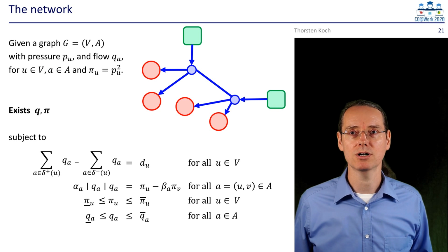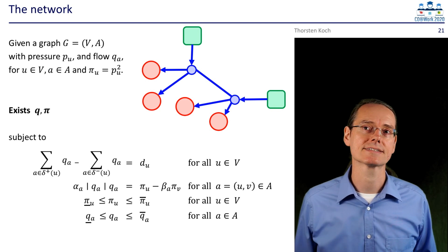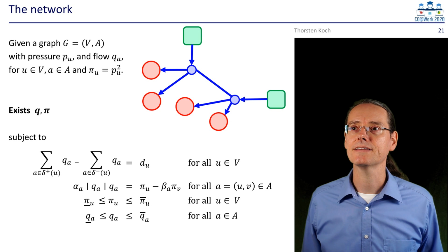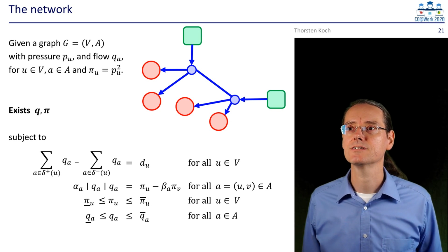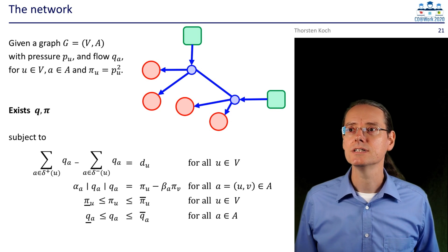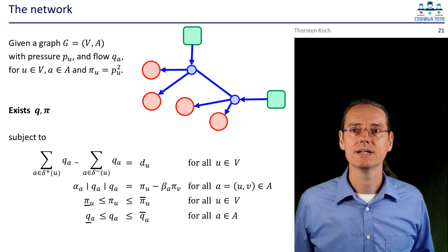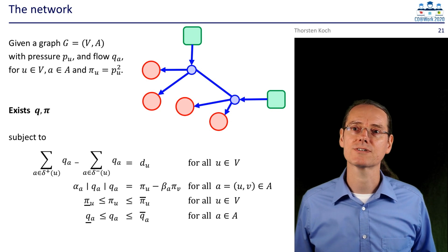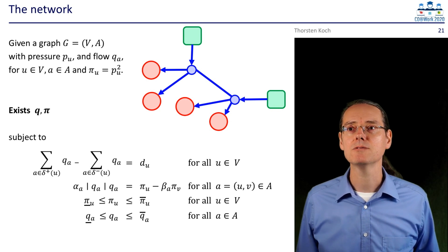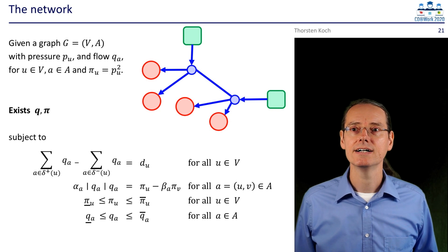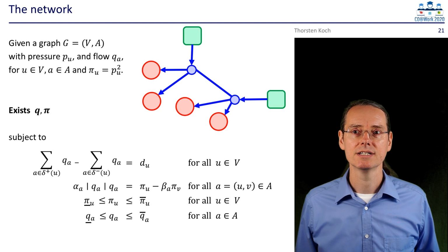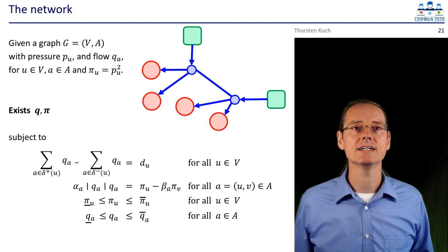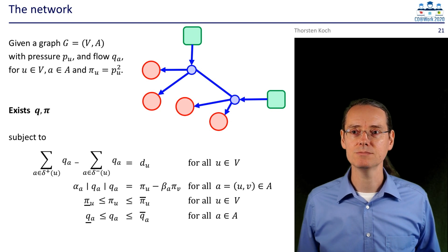Now let us build a network. Let us assume 2 entries and 4 exits like this here. You have to understand this is all coupled through pressure. So the input pressure at the entries is given, so it proliferates through the network. Let us assume for the moment that the amount of gas entering and leaving is balanced. Then we can compute the pressure at the exits. Now if we change the pressure at any outside point, the whole network changes. So it's all coupled. And there is a distinct equilibrium, and this is called the line theorem, which I will show you.